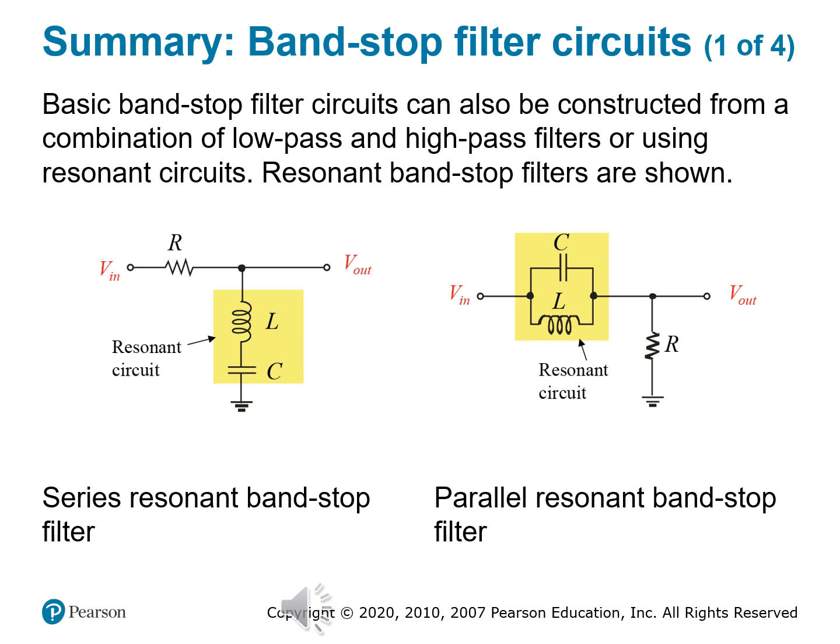So again, you have two different flavors of this: the series resonant band stop filter, the one on the left, and the parallel resonant band stop filter, the one on the right. I'm going to break down the circuits for you. In the series configuration, we place a resonant LC circuit in parallel with the load, and this LC combo is tuned to the frequency we want to block.